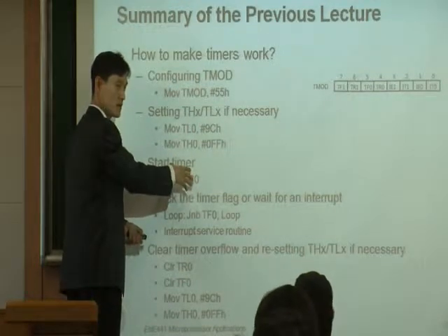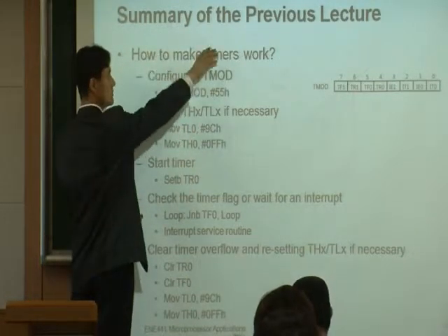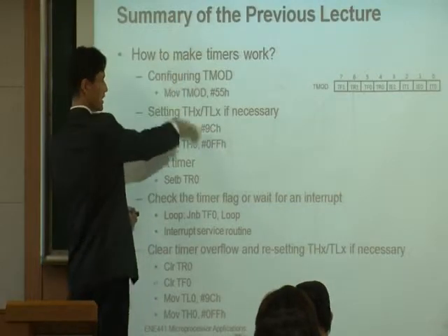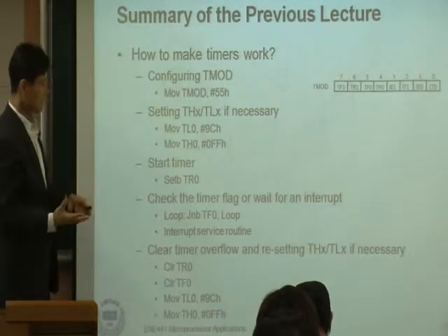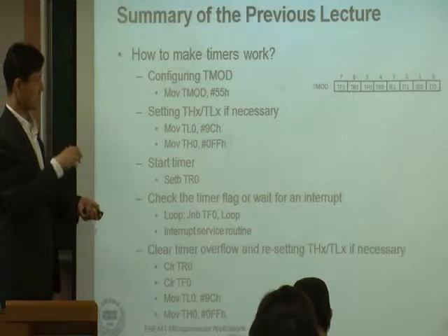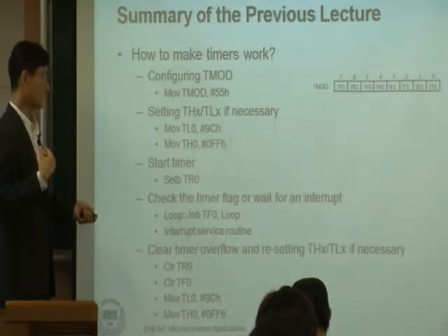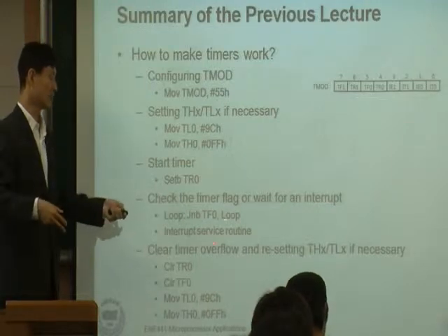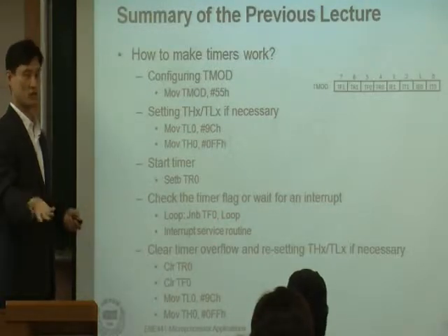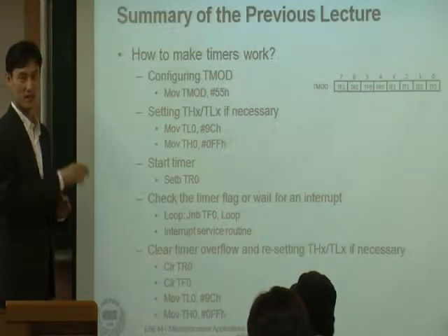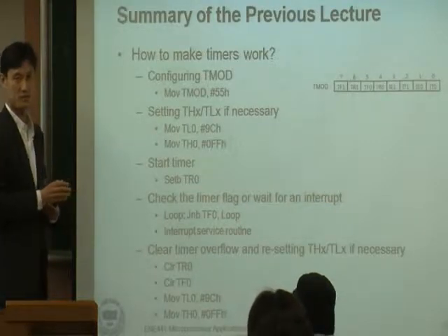That's a better way. Once you enable the timer interrupt first and run the timer, whenever the timer interrupt happens, software will get the timer interrupt. Then you jump to the timer interrupt service routine, and you do whatever you want in 1 millisecond inside the interrupt service routine.